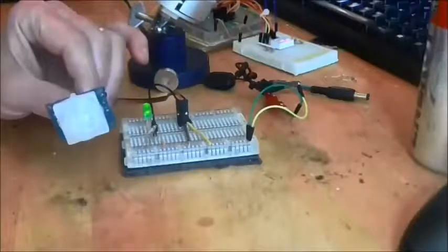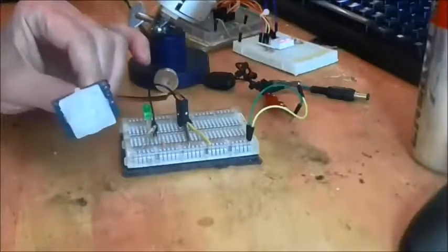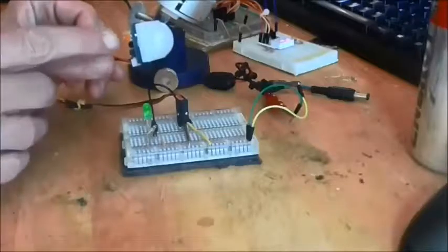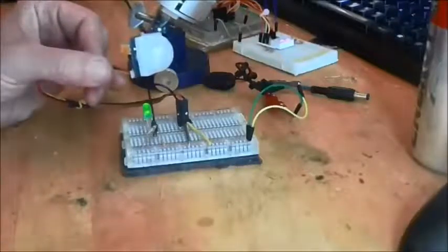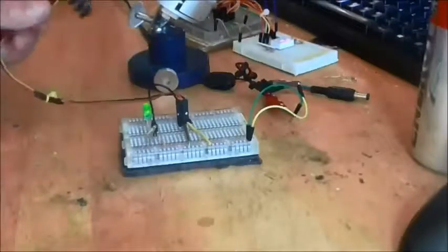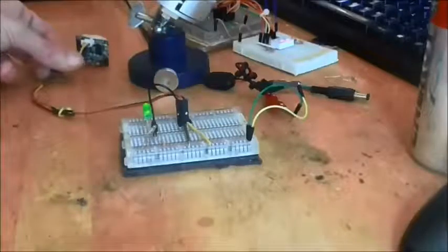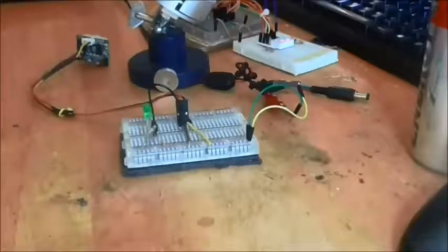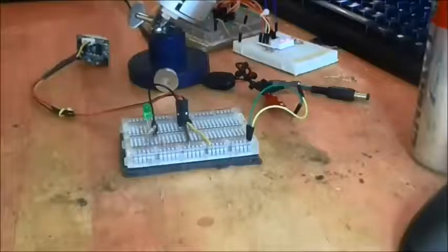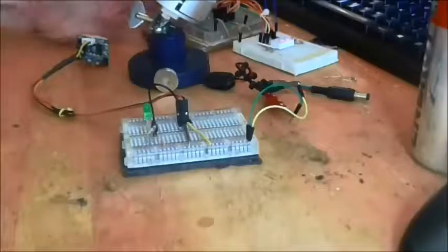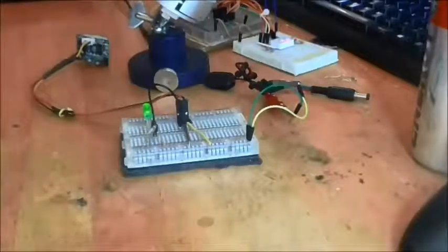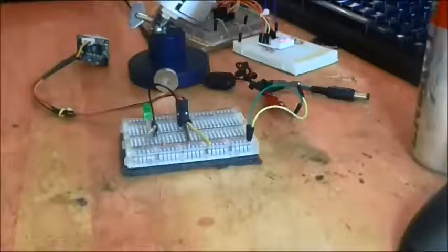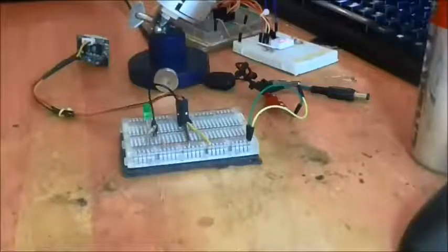And the length of time the signal's output for can be altered by this orange potentiometer here. So I'm going to leave it quite a short time, and if I put it back and let it settle down, what should happen is that as I put my hand in front of it and move away, the LED should go on. And that signal is what I'm hoping will work the input of the gate we've just seen.